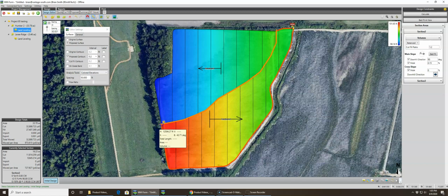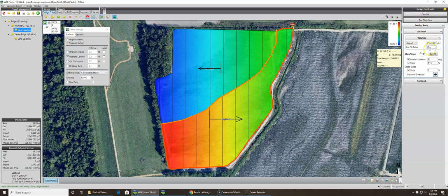import-export dirt, you grab your measure tool, you go around your border, calculate your border, just say we're going to put it around the bottom of the field. Now that's 2,142. You can either just do a yard per foot and hit export, 2,142, do it that way, or you can do length times width times height divided by 27, and then that would be your export yards you would put in there. Okay, then be sure to hit calculate.